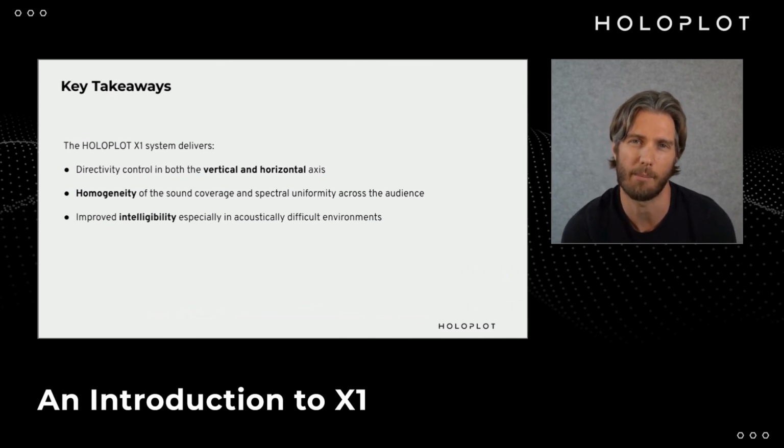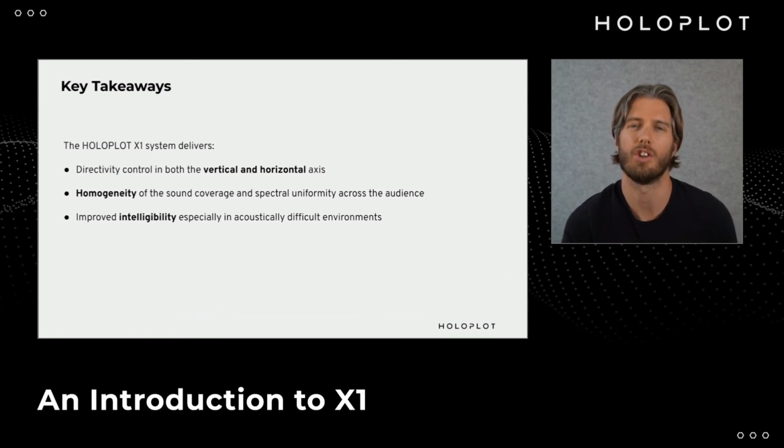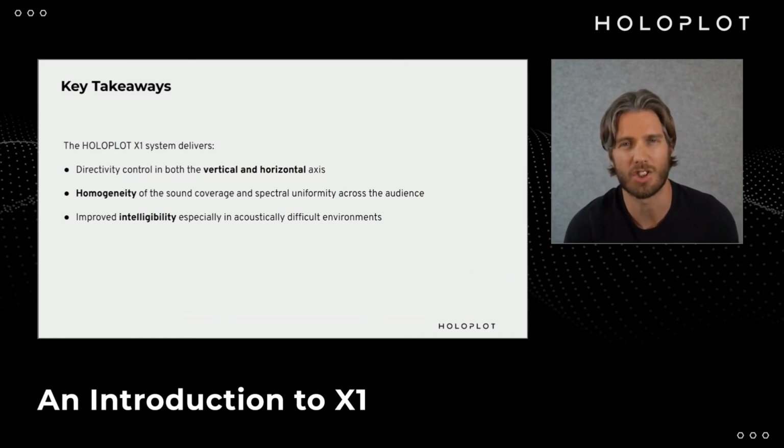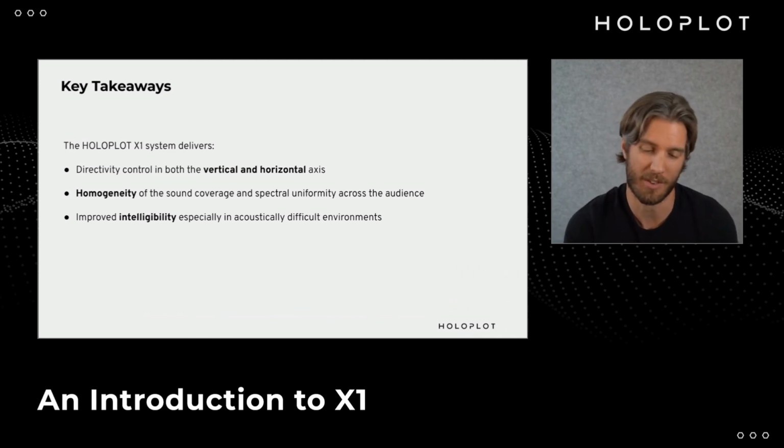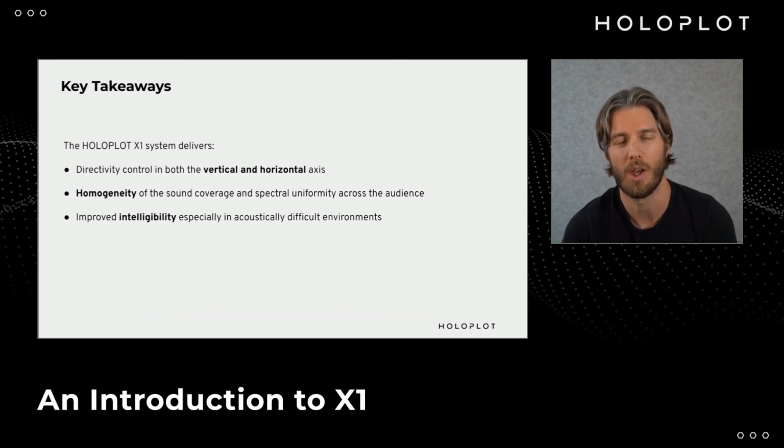That's worth talking about because a lot of the design that I started doing back when I was an acoustic consultant, as a PAVA engineer, was in acoustically difficult or hostile environments like train stations, major transport hubs, airports, places where you get very loud background noise and very high reverberation. Using these features that we've looked at so far in auditoriums, but in venues like that, and being able to control the sound, you can really drive up the intelligibility in spaces like that too.